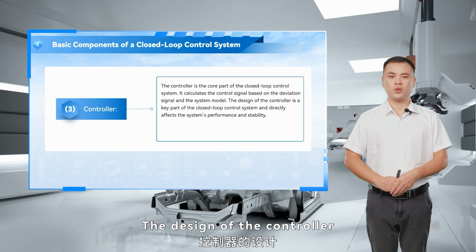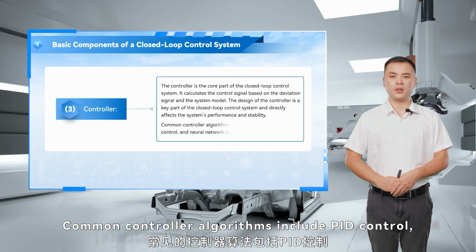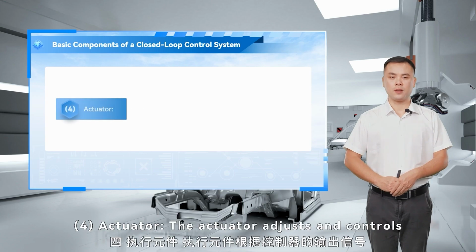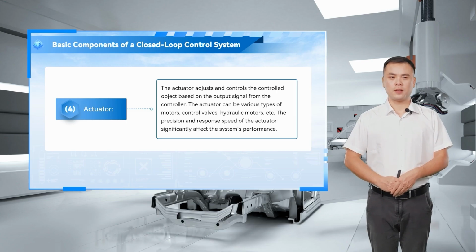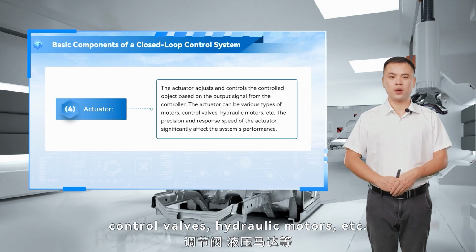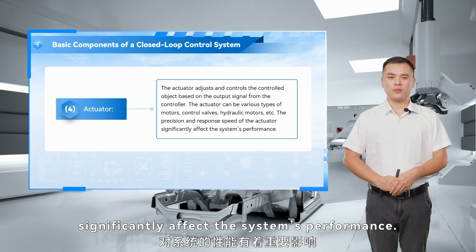The design of the controller is a key part of the closed-loop control system and directly affects the system's performance and stability. Common controller algorithms include PID control, fuzzy control, and neural network control. 4. Actuator. The actuator adjusts and controls the controlled object based on the output signal from the controller. The actuator can be various types of motors, control valves, hydraulic motors, etc. The precision and response speed of the actuator significantly affect the system's performance.